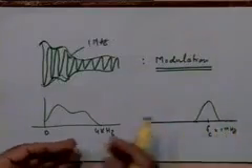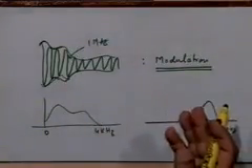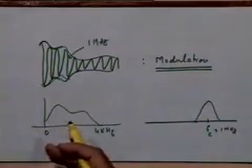And this bandwidth of 4 kilohertz is a very small fraction of the center frequency of 1 megahertz. So the lowest frequency components and the highest frequency components are all of the same order, right? 1 megahertz minus 4 kilohertz to 1 megahertz plus 4 kilohertz, they are all of the same order of 1 megahertz. So the antenna size required to radiate this would correspond to 1 megahertz rather than 4 kilohertz.